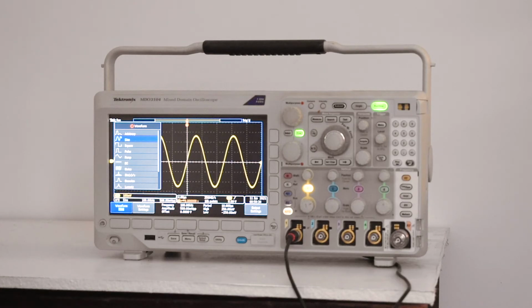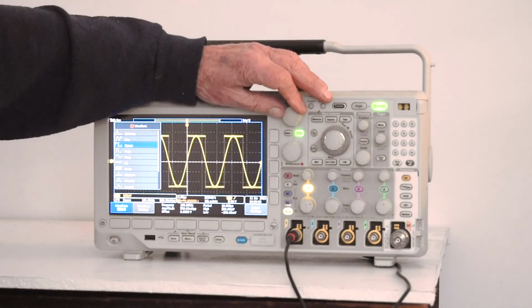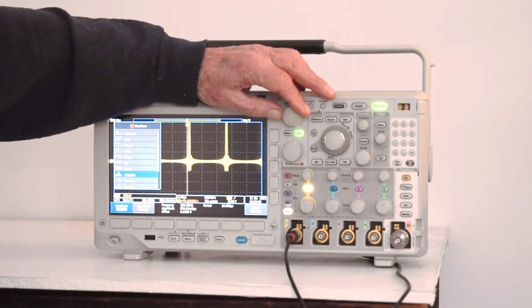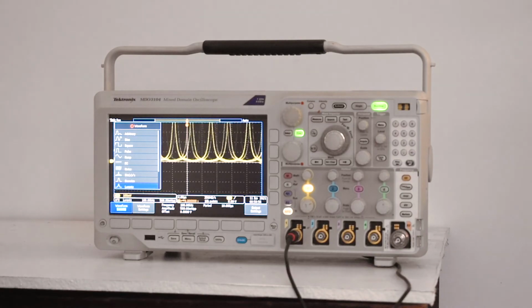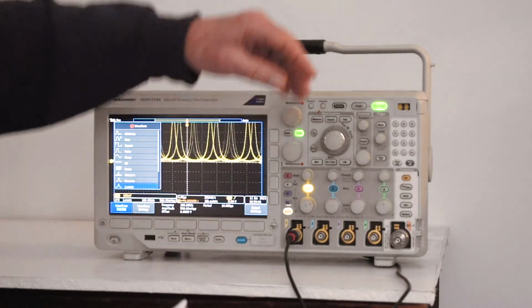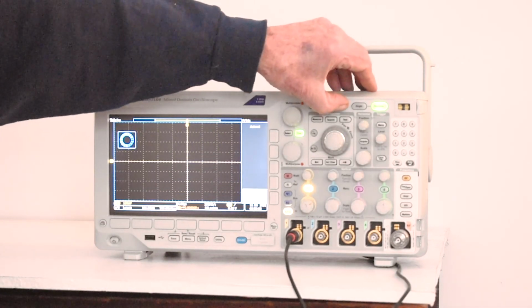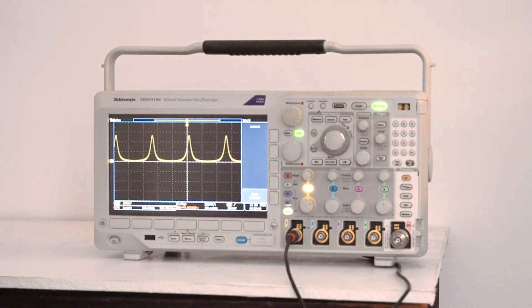Many of them have similar default parameters, but when you scroll down to Gaussian, Lorentz, exponential rise, exponential decay, and Haversine, the waveforms are unstable and do not provide useful information. Pressing Auto Set corrects these settings. Auto Set is frequently used, and here again, if nothing, including default setup, seems to work, Auto Set is frequently the answer.